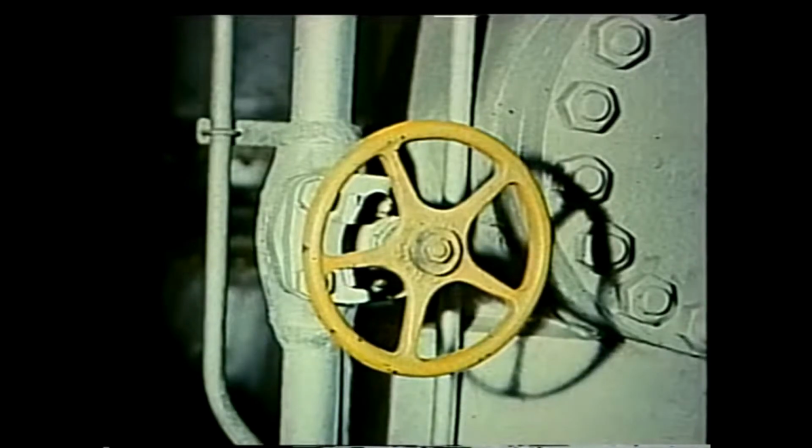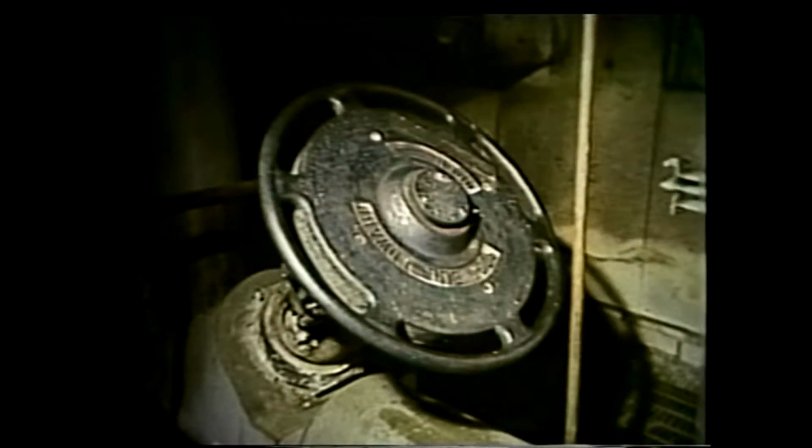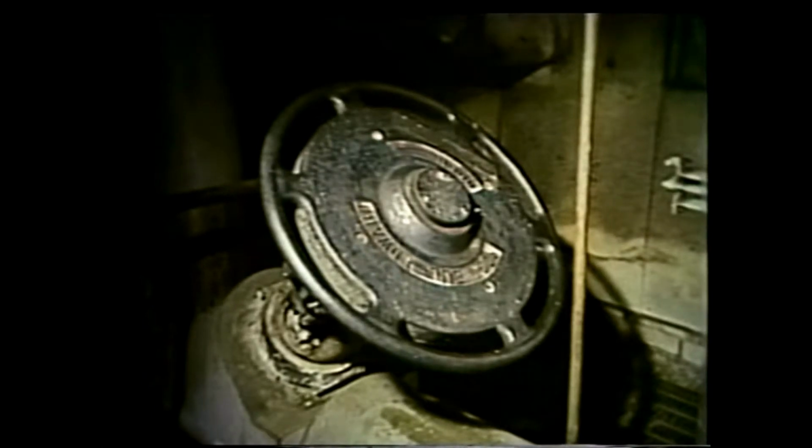Now we'll find out how some of these hand wheels and mechanical operators work to make the valves open and close and regulate flow. The most common type of operator is the hand wheel. This valve has a modified hand wheel called a knocker. It's a type of hand wheel that is usually found on very large hand-operated valves, which are designed for heavy-duty service. The hand wheel on the knocker valve is weighted and has approximately a 1/4 turn play.